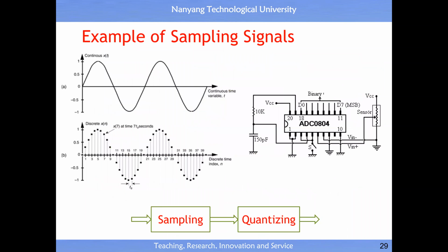In the video, I already explained this to you. Then what is sampling? Because this is a time function, continuous time has infinitely many points. But we just use discrete time now. Let's say every 1 millisecond, I do everything. It should be good enough, right? So every 1 millisecond or every second, depending on the application. That means converting continuous time into discrete time. This is called sampling. I only do the measurement at discrete times, not continuous time.